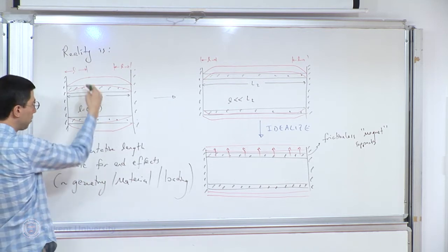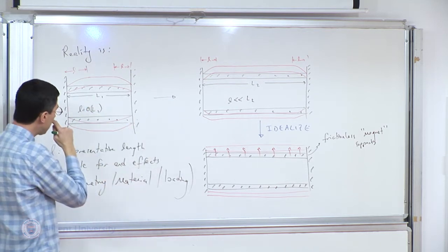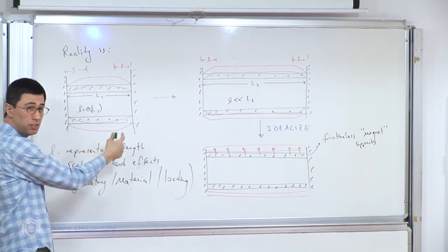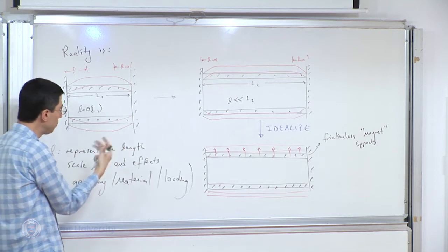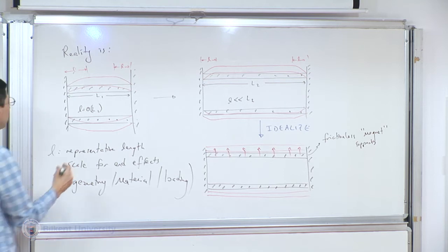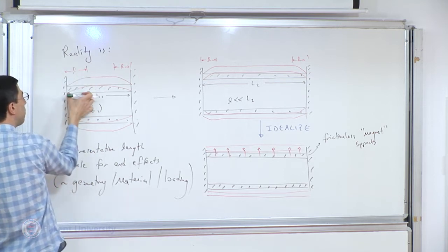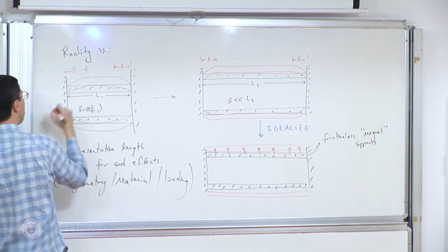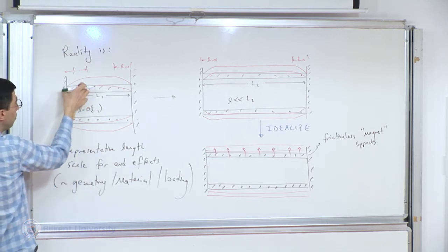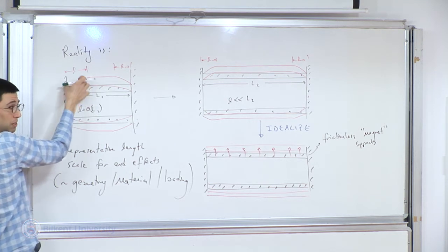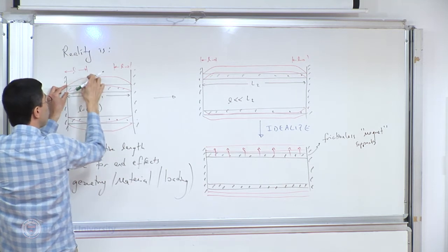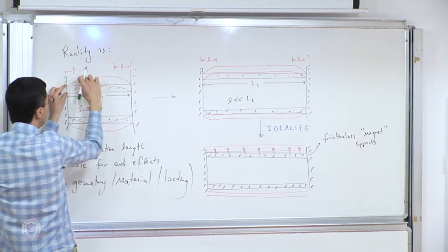In this deformation, there's obviously radial displacement in every case. There could possibly be a displacement in the z direction. That is something that is not very easy to convince you of, so I'm going to show you an example. Essentially, because of this strange deformation, the displacement in the z direction, uz, is not necessarily zero. For instance, in this region, this is sort of rotating. There is perhaps some displacement in the z direction. This portion is actually somewhat subjected to bending. You will see in the numerical example.